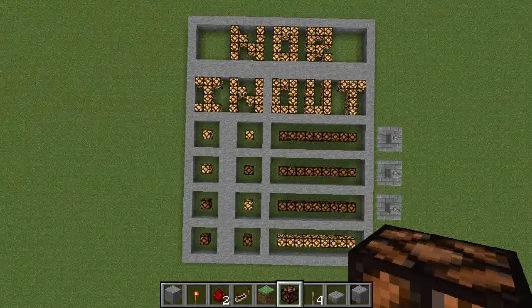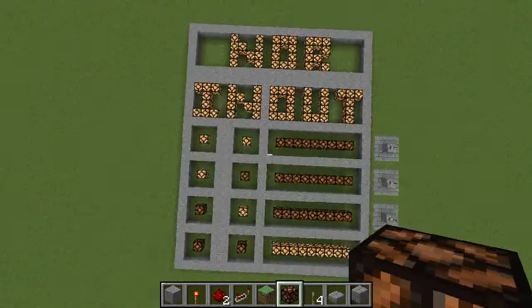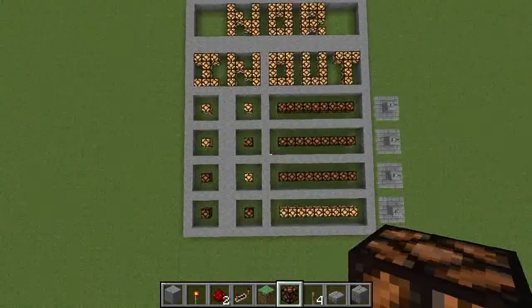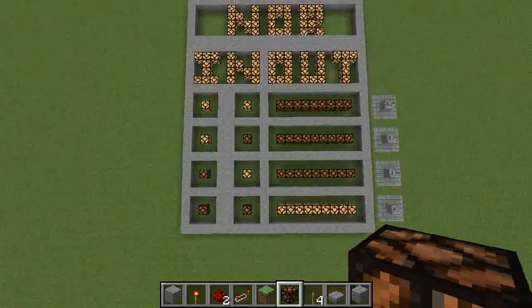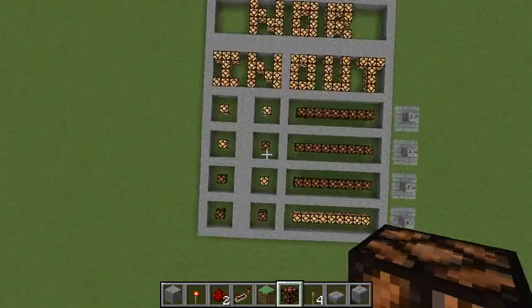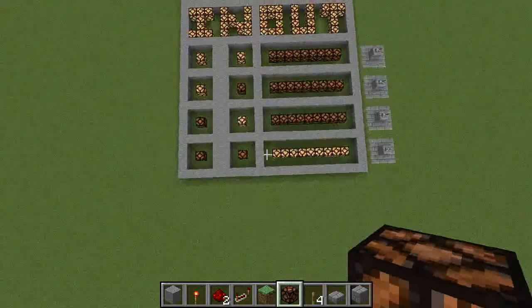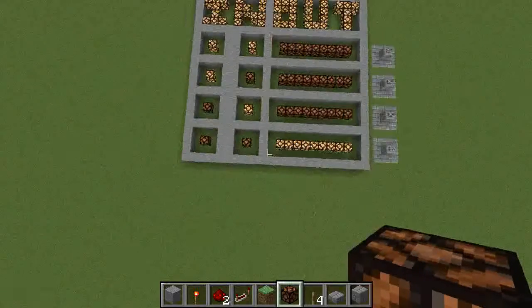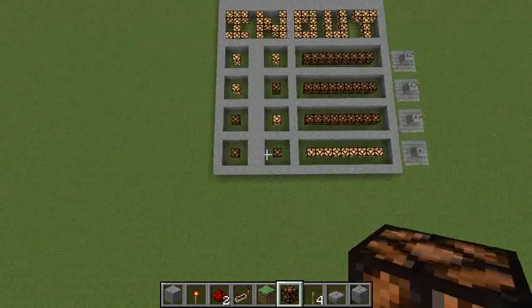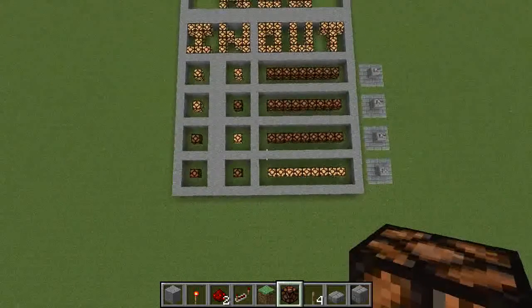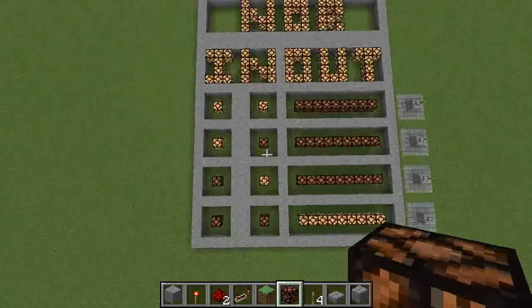Alright guys, I am back with our next gate. This is the NOR gate, and it's pretty much the same as the OR gate. Well, actually, it's the exact opposite, which makes it pretty similar. For all the inputs that led to an on output for the OR gate, we get an off output, and for the one input that gave an off output for the OR gate, we're getting an on output, if that makes any sense. So we can just look at that a little more simplified.